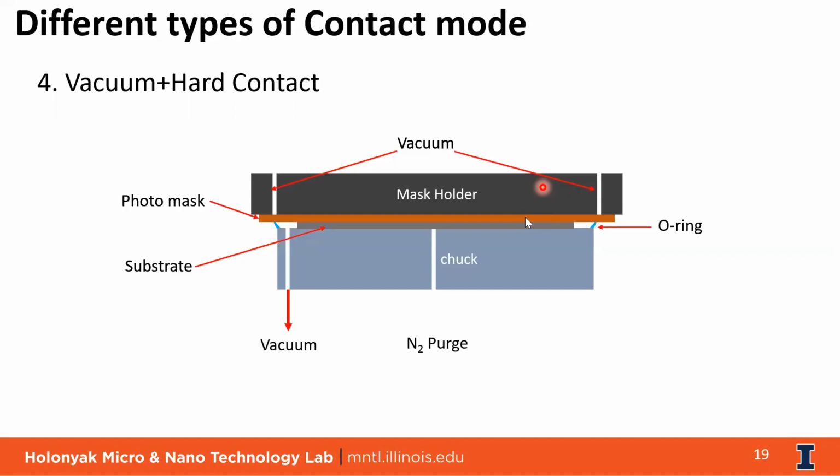Okay. So the main reason is that chrome can be dissolved in piranha solution. So that is the reason we are diluting the chemical. Instead of using it at high concentration, we use very, very low concentration. And again, we do not use it for more than 10 to 15 seconds.